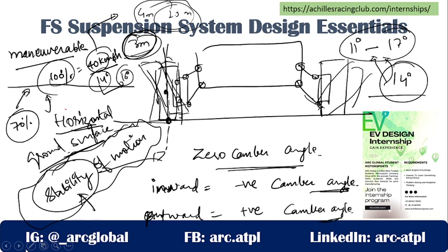At a very high speed, say for example, I'm moving a vehicle at 100 kmph, you will find that at that point you do not have much control over the vehicle. What do I mean by that? I am planning to move my vehicle at a certain speed, or to have a certain acceleration, but it is not responding in that way. It is either higher or lower. I want my vehicle to turn by this particular angle, but now my cornering angle increased. So now these things are not under your control. It means the maneuverability is being reduced.